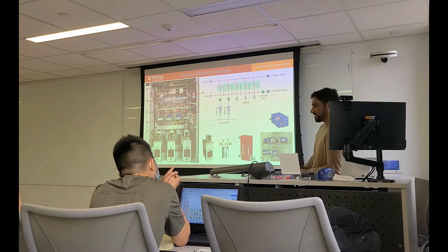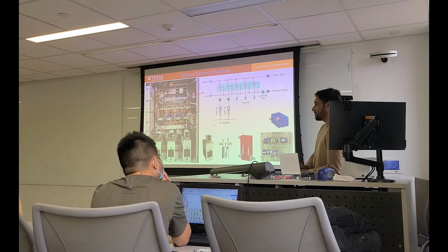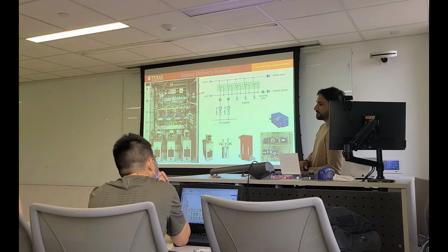Nitrogen is an inert gas actually. It is very difficult to break the inert gas. In the case of nitrogen, you need a very high temperature to break it, around 1600 or 1900 degrees centigrade. But we have observed that when we use hydrogen with similar growth conditions, hydrogen gives better morphology and a better growth rate than nitrogen.